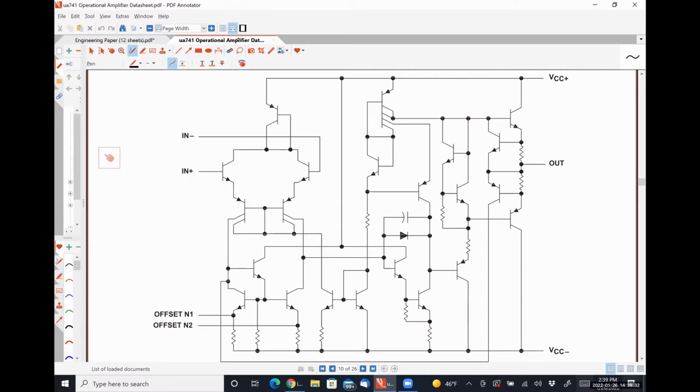So all that really means is you could take this device and you could actually short out the two inputs and see some small output signal due to the way that these devices are constructed. Those two pins are used to bring that offset down to 0 so that no input gives you no output. Those two pins mean absolutely nothing to us in this class whatsoever, so we're not even going to bother to draw them, okay?